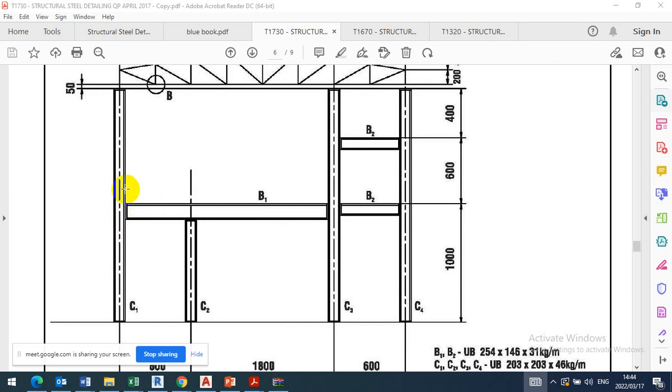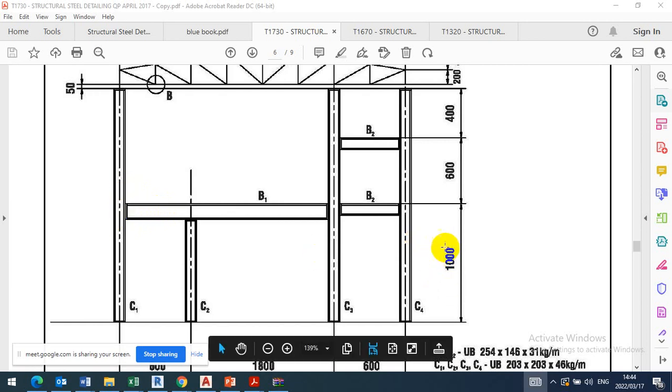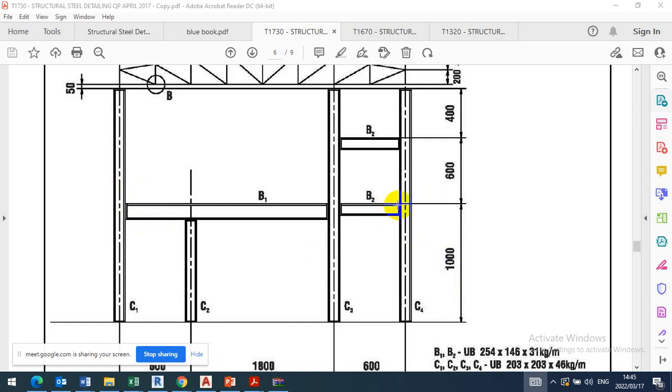It's not going to be welded on the column, but there must be bolt hole positions on the column at a distance. You can see this is 1000, it's on top of the beam. So you need to come half here, by half of the beam height, whatever the beam height of beam 1 or beam 2 is, so that you know that it's in the center. It's going to be connected somewhere in the center there, if we follow. So which is also happening here.